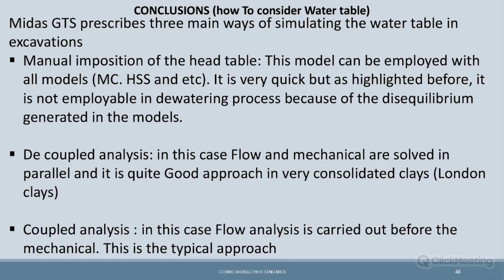And then there is the decoupled analysis. In this case, flow and mechanical are solved in parallel, and it is quite good in very over-consolidated clay, for example, in some cases in London clay. And then the coupled analysis, in this case flow before the mechanical. This is the typical approach, the most important.